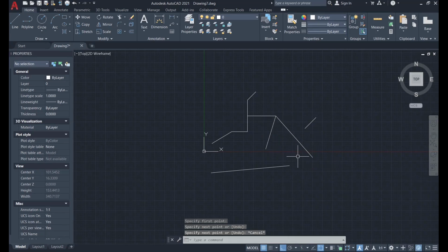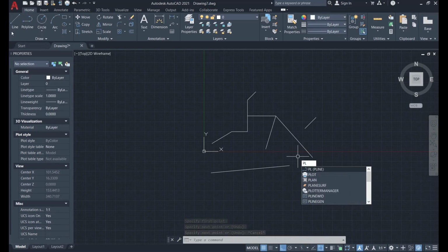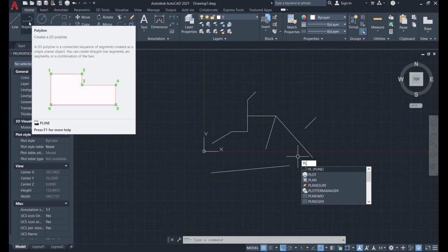Is this similar for the polyline? The shortcut for the polyline is PL. So also you can drag your cursor over it. You will see that it is used to create segments that are linked between them and will manage to draw a closed object.